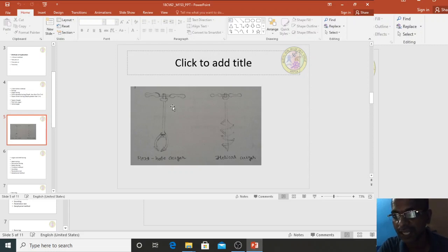If you take this auger and place it on top of the ground, press it and rotate it in a clockwise direction, the soil will be sheared and will start collecting in this particular portion. Once it is full, the movement will become free. You can conclude that the soil has filled this portion, and take out the auger. In that way we get the soil sample. That sample is totally disturbed and therefore it is called a disturbed sample. This post hole auger is used when the soil is comparatively soft in nature.